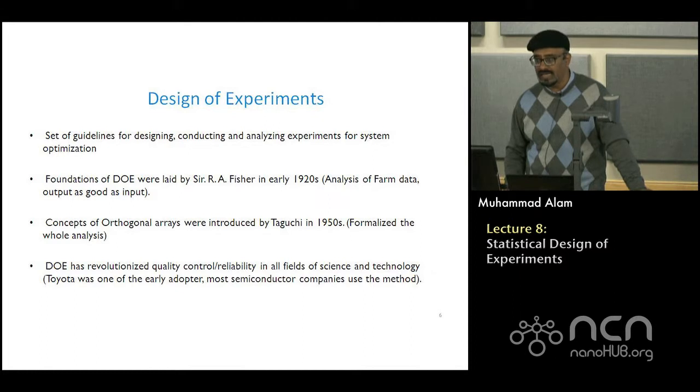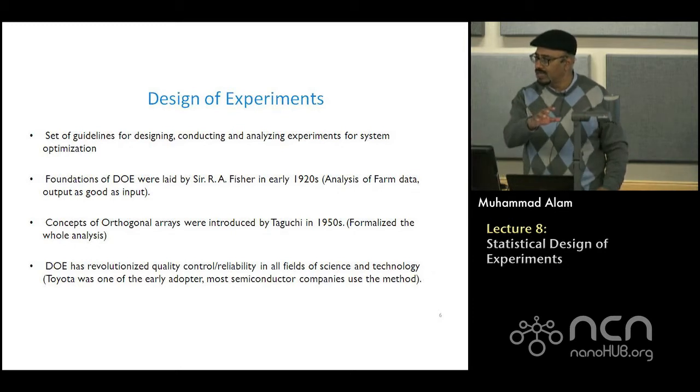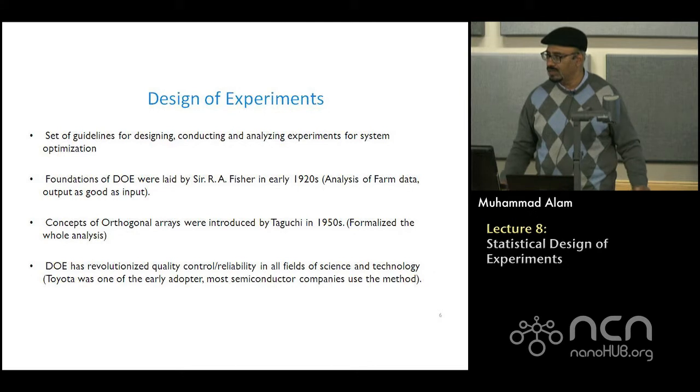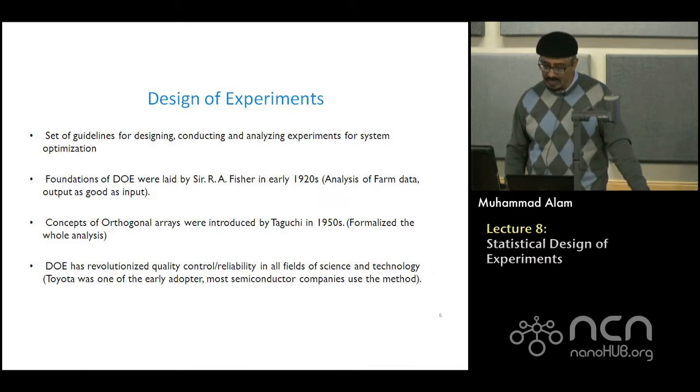For example, often Intel, when they want to design a microprocessor, they may run 400 of these wafers with slight variation, some with a little bit more doping, some with a little bit more processing temperature, and thereby they optimize it. But how do you handle it when you have about 1300 steps? How do you optimize such a gigantic optimization problem? With 400 wafers, you are lucky that you can do it, and yet that's very expensive.